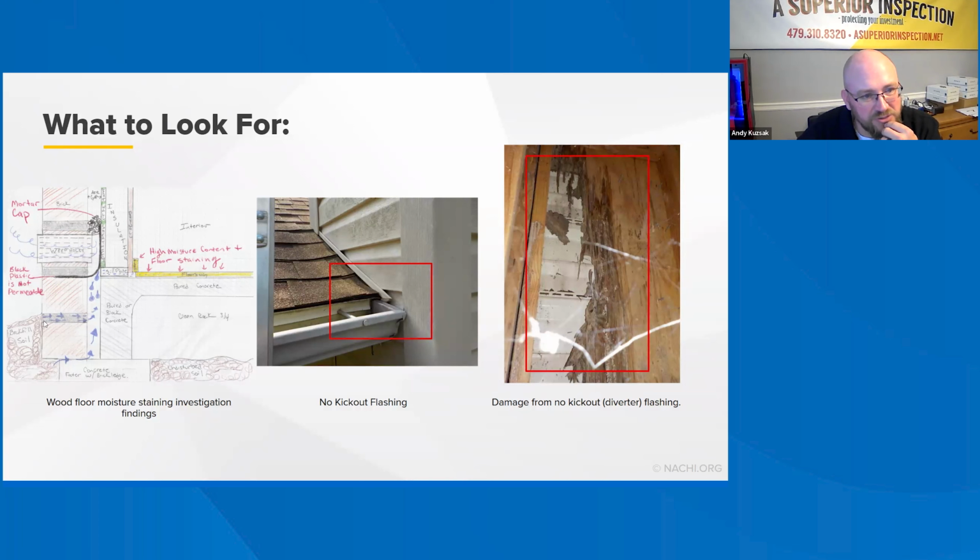And so moisture was traveling through the brick, going up the air gap. And because they used the 6 mil poly, they actually left the sill plate exposed. And so the moisture traveled through the sill plate and into the wood flooring. And so the entire perimeter of this house, they had a blonde type wood flooring, and around the entire perimeter became a lot darker brown instead of blonde.